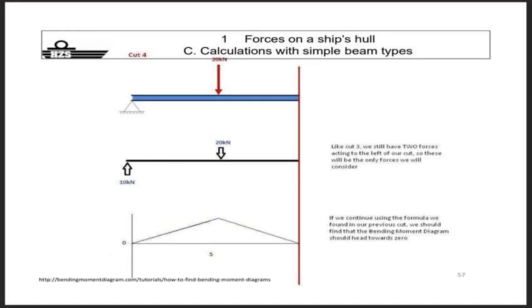That was the first calculation. I hope you still know a bit what this is, a bending moment diagram of a simple beam. It gives you bending moment values internally at different positions along the beam. You can give restrictions to bending moments, and that's what the naval architect does when you compare a beam to a vessel. But those bending moments lead to stresses.